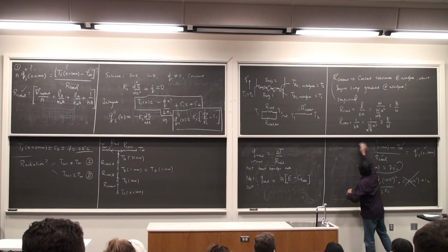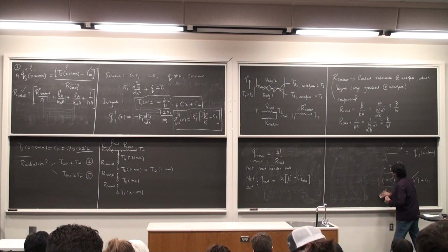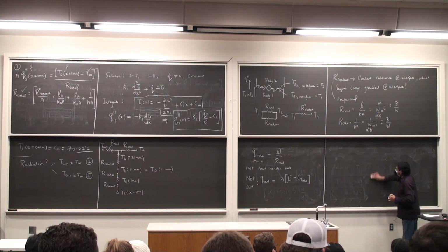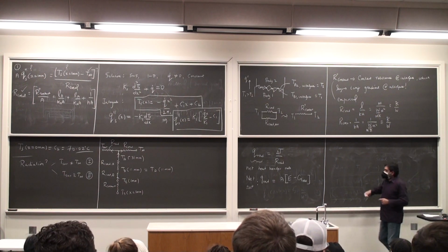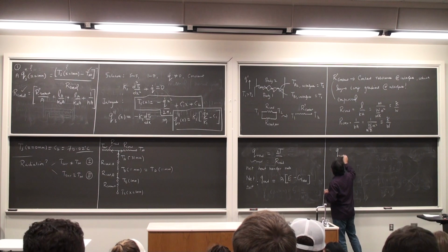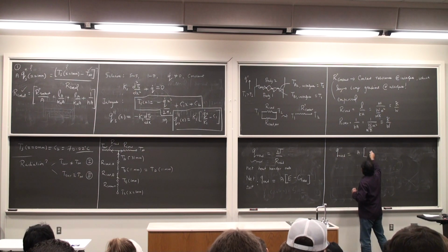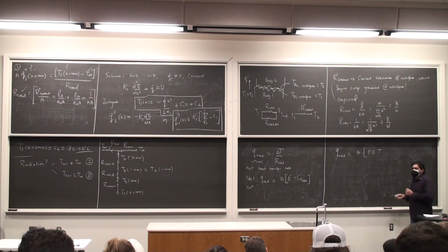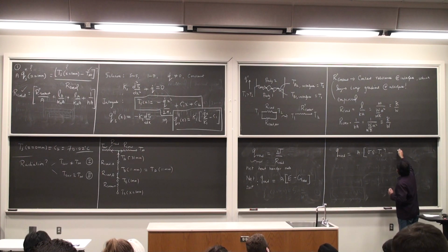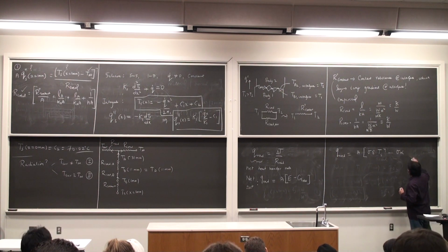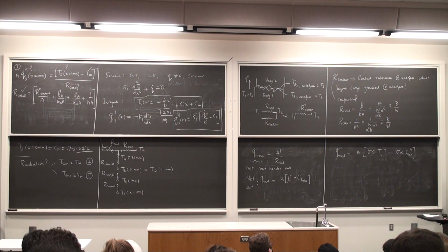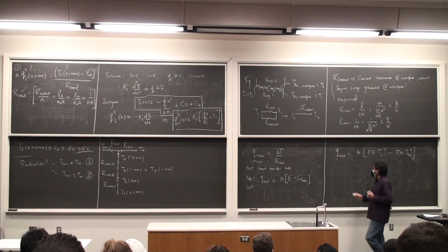Bear with me for a few more minutes and we'll be done. If I substitute, this is A times sigma epsilon temperature of the surface to the power 4 minus sigma times alpha temperature of the surrounding to the power 4. And if I employ the fact that this could be a gray surface, so alpha is the same as epsilon.